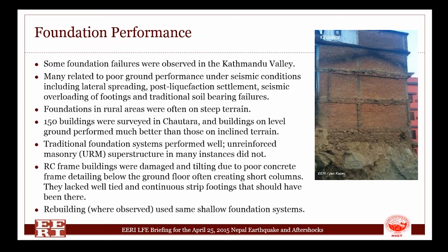Foundations in rural areas were often on steep terrain, geotechnically slightly more competent, but when we surveyed about 150 buildings in Chautara, it became fairly apparent that the buildings sitting on steep or inclined terrain performed worse than their counterparts sitting on level ground.